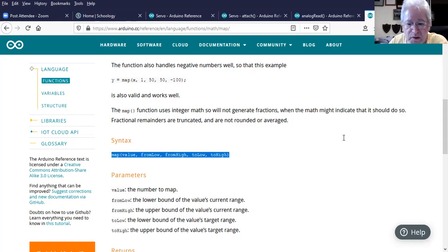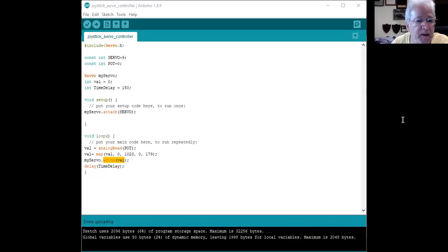So let's take a look at the code and see exactly where that was taking place. Okay, you can look at these functions to digest what I just said, which is pretty quick. So here we're doing an analog read of the analog pin for the potentiometer, getting a value. We're using the map function to translate the value into a new value with a smaller range. And then we're writing out to the servo to change the position. That's basically what's happening. So with that said, let's now examine the document camera and see how this behaves.